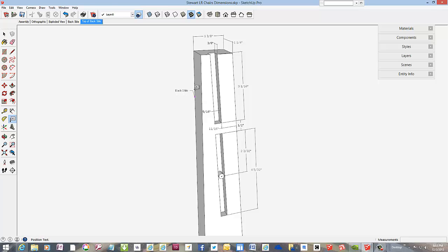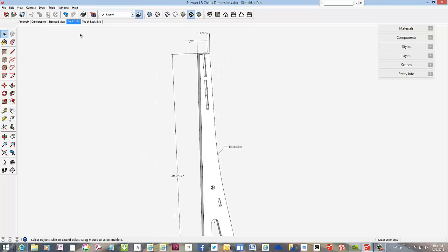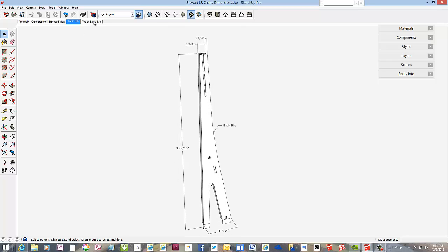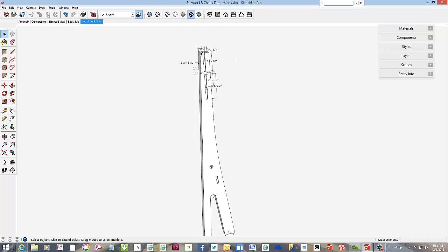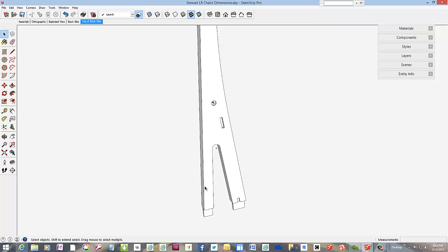And I'll label it again, and now go ahead and select all the dimensions and text. Probably be easier just to select everything here and then deselect the actual component rather than clicking on all the dimensions. And then go up to the layers toolbar and pick detail. So now all of those dimensions will not show in the previous scene, and only detail dimensions show up in this scene. So it's working well.